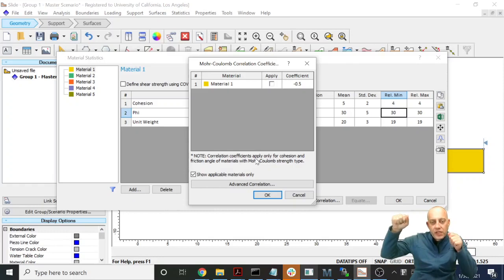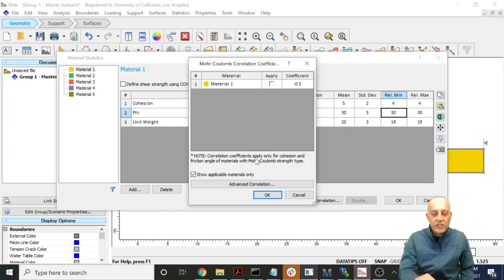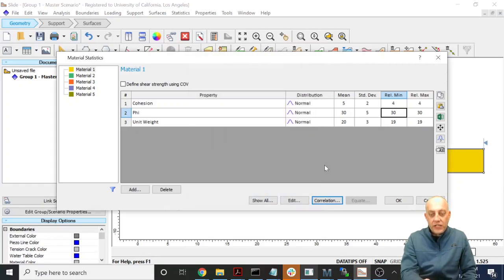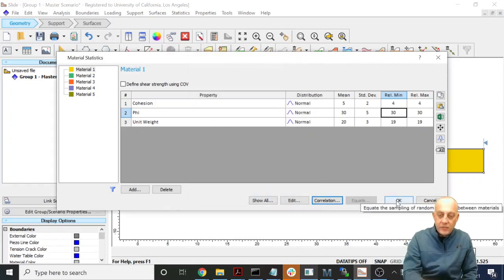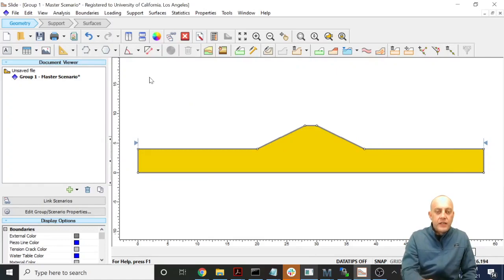Well, you could also slightly increase the cohesion and slightly decrease the friction angle, and it would fit almost the same. Similarly, you could decrease the cohesion and increase the friction angle, and it would fit almost the same. So for a given set of circles, for a given laboratory test, you're going to get negative correlation. I'm going to leave this as just no correlation. We'll leave them uncorrelated. We can add that in later to see what it looks like.